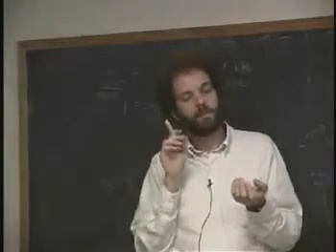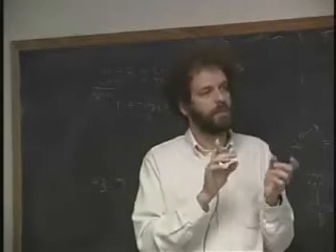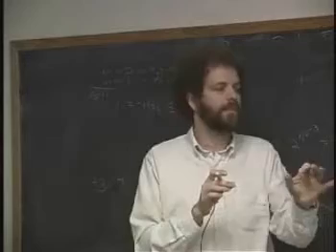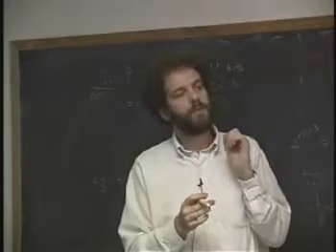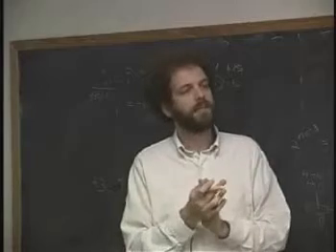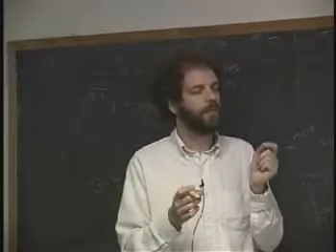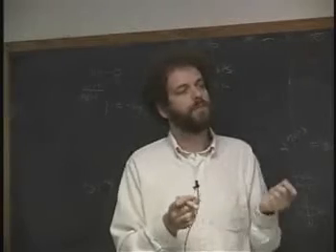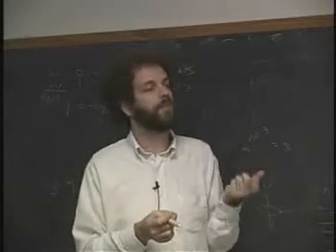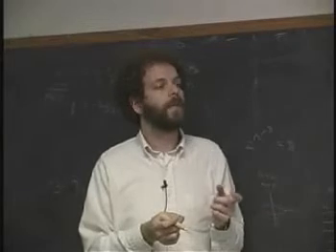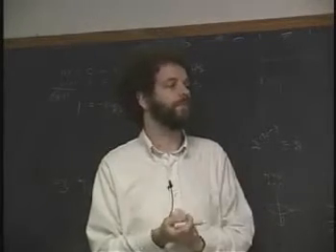But because the data is completely predictable, I'm sending you 0 bits of information. The units are the same, but one's bits of data that I send you, the other one is bits of information. If I send you a stream of data that has the maximum amount of information, in other words, 1 bit of information for every bit of data that I send, what would you expect the bits to be like? Each one would have a 50% chance of being a 0 or a 1, and they would be independent of each other. So it would sound like a random stream of zeros and ones.